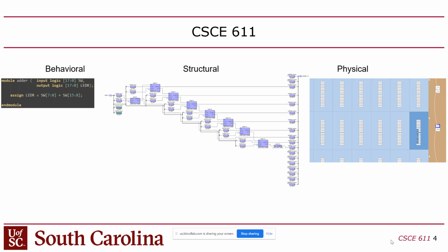So we still have this idea of behavioral, structural, and physical. Now it's a little bit of a misnomer though, because it turns out that when you write code in SystemVerilog, you write some behavioral code, but a lot of the code you write is actually structural. So you're actually building a structure, like you're instancing and connecting modules, but you're doing it in SystemVerilog. Typically in a SystemVerilog design, it's hierarchical. So you've got designs that are comprised of smaller designs, and those smaller designs are comprised of smaller yet designs. But then at the very bottom, at the leaf nodes, is where you have your behavioral code.